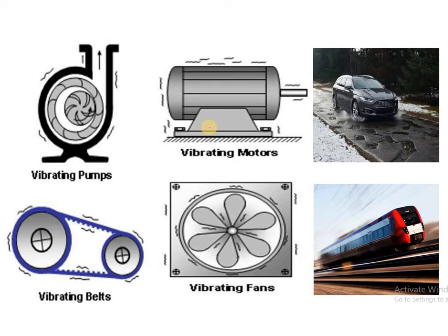Again, at the same time, non-homogeneous material. When we are using a system for a long period, slowly the amount of friction in between the two parts goes on increasing and some amount of wear is there. Due to this, there is some amount of unbalanced mass which leads to unbalanced force. So this is how the vibrations are generated in the system. These generated vibrations are nothing but the forced vibration.